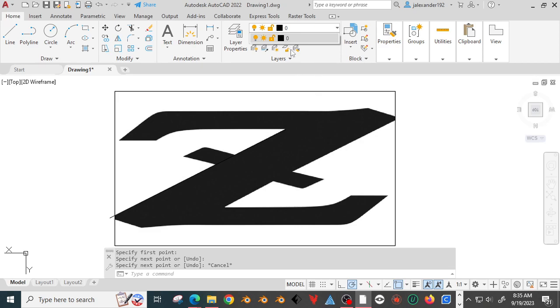So it's not much, but you can see if I pull it down, it gives me options. I can turn layers off or freeze them. And these two buttons pretty much work the same. It hides the layer. And locking makes it so you can't edit it by accident. And then the last thing here is the name, 0, and the color of the layer.